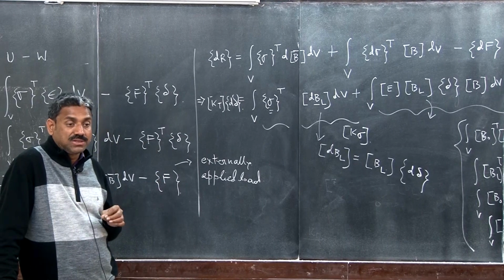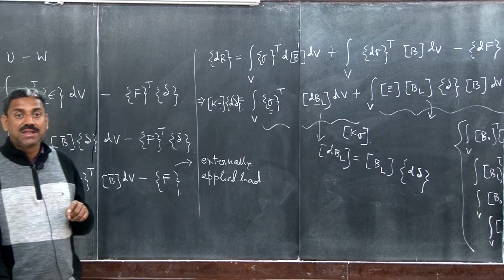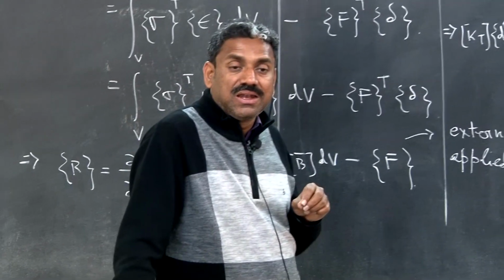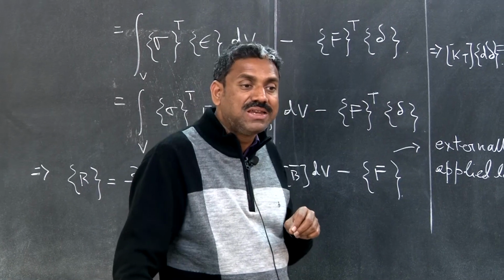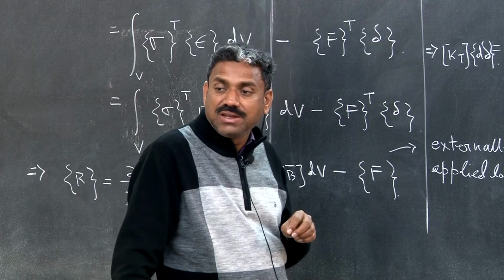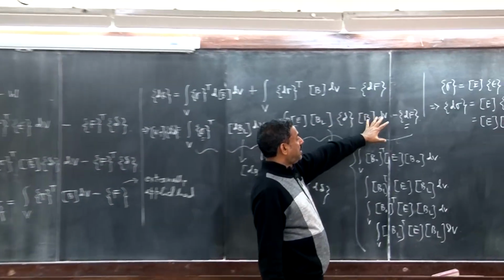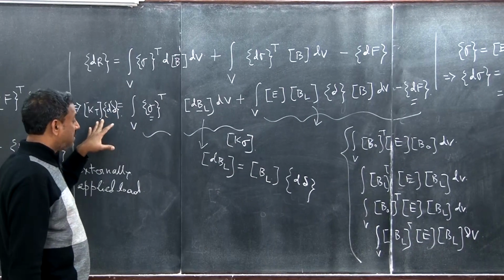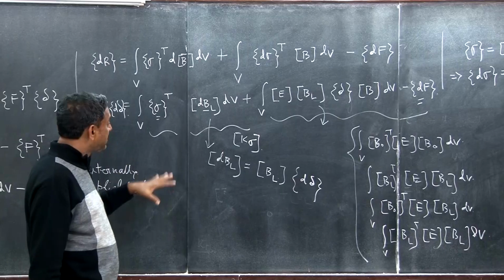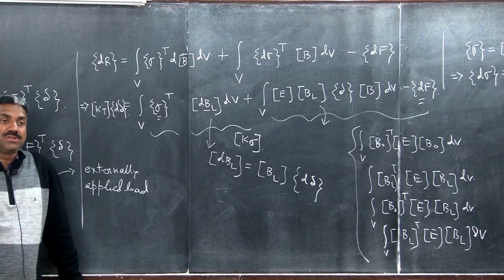Geometric nonlinear analysis, you have to do full analysis. But when we are doing linearized stability analysis, that means we are linearizing the system of equations to include only the linear term. That's why it leads to an eigenvalue problem, and that's what we are truncating. We are truncating this part, and we are just making the material stiffness matrix, the linear stiffness matrix, and then the geometric stiffness matrix, and then solving the respective eigenvalue problem.